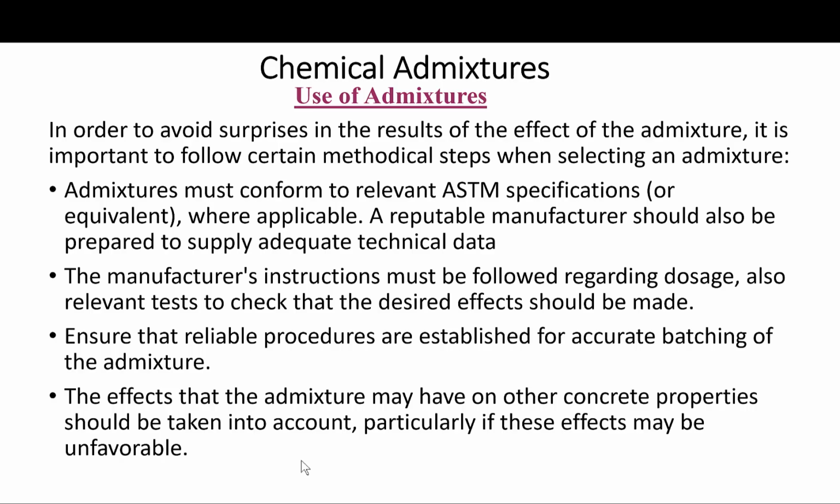So it is particularly important that these tests be run using job materials under job site conditions, because the precise effect of an admixture will depend on many factors, such as cement composition, aggregate characteristics, and impurities in the aggregates, mix proportions, presence of other admixtures, type and length of mixing, time of addition, concrete temperature, and environmental conditions.